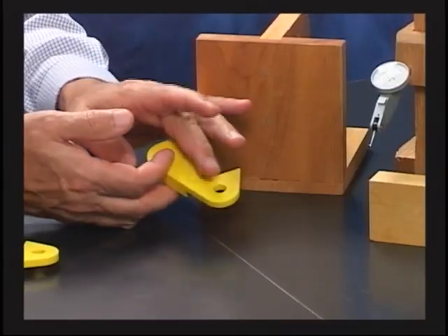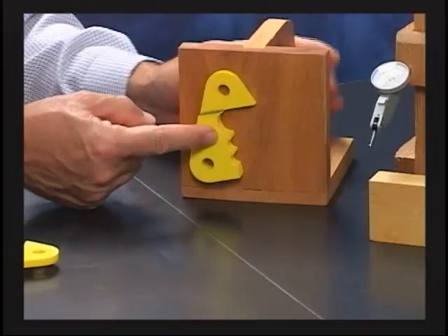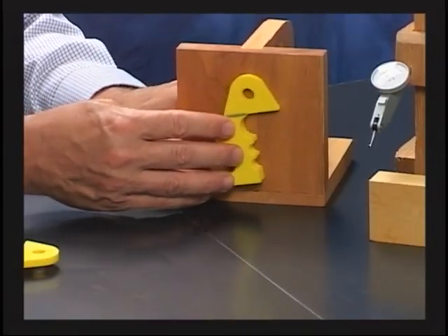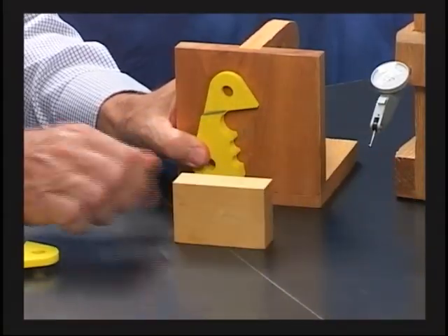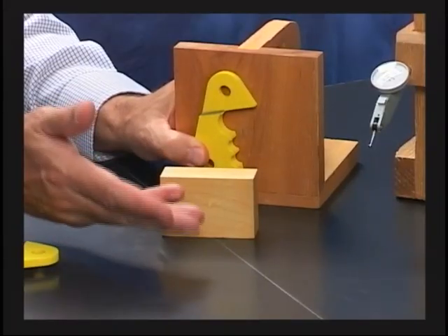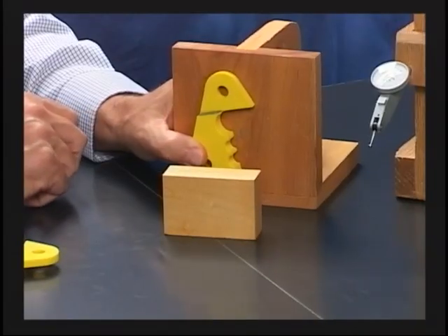Remember what datum A was. Datum A was this back face, so they would probably bring it up against the angle plate. If they brought it up against the angle plate, you see it's contacting on the high points. Now we have to line it up in this direction. What they might use is a gauge block. This is a gauge block. We sometimes call them a 1, 2, 3 block. It's supposed to be theoretically exact. They have tolerance, but it's within gauge tolerance.